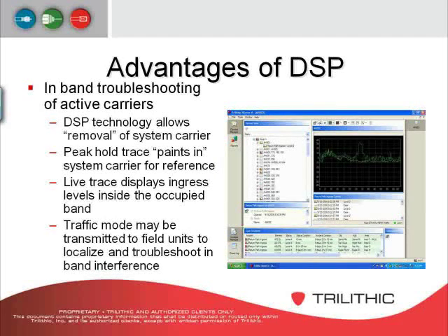So not only will the NOC be able to see up under that modem carrier or the active areas, you could send that same display to your field units, and your field unit will see the same thing that the NOC is seeing. So it makes their troubleshooting a lot easier when the modems are experiencing slow speeds, and we know that it's because some ingress is falling up under the carrier. You'll be able to see it, troubleshoot it all the way to the point of origin.